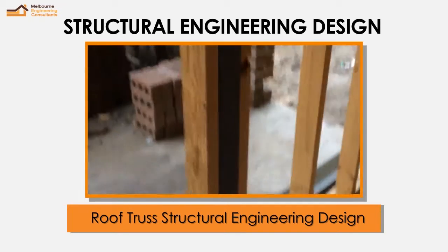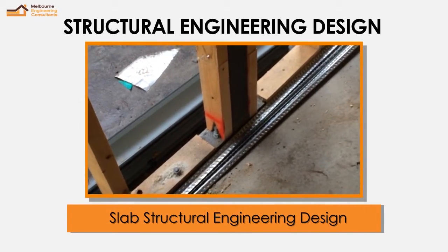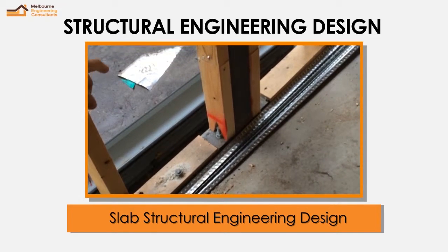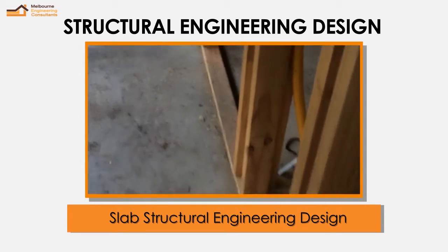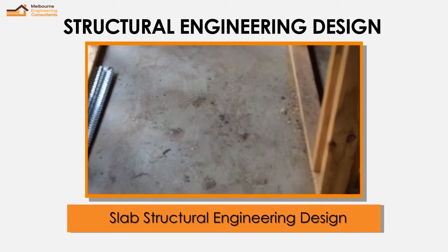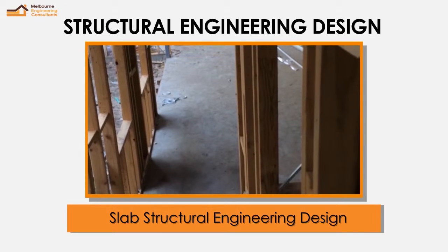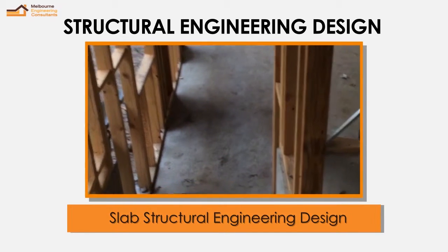And on the base there is a post connection to the ground which is on the concrete, bolted to the concrete with M16 bolts with the base plate. And here the concrete is again, as we discussed in the video on the structural drawings, on the waffle slab, and this is a step down here which we already show the detail on our drawing, the steps and everything.